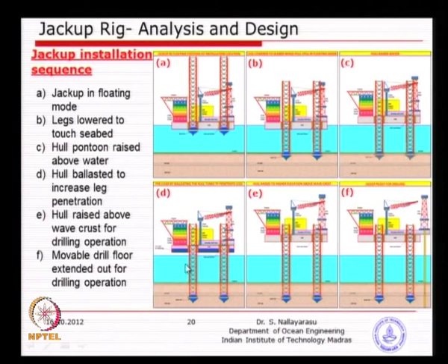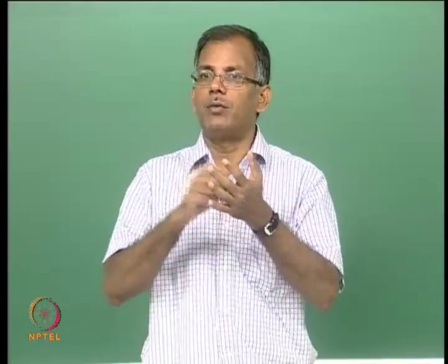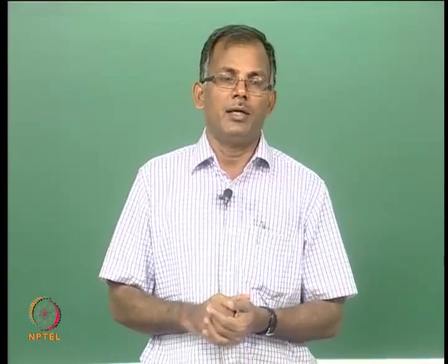And then you flood water inside the hull, just artificially flood, pump water from the sea and put it into the hull, make it even heavier, and the hull will try to go down because of the additional weight, and the leg will penetrate below. As much penetration as has happened with predefined preload, we have to define what is our preload. Depending on type of soil, depending on size of spud can, we will calculate. I need 20 meter pre-penetration. In order to get 20 meter penetration, how much load do I have to create? So, you will pump only that much water.